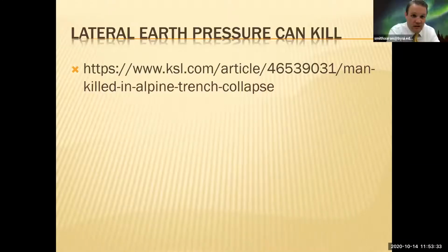Yeah, you will have knowledge that the common construction worker won't understand about soils. If you're ever on a site, you have a responsibility to warn people of the safety hazards they're unknowingly entering into. If you see folks jumping in and out of trenches installing a utility line, and it has pretty steep slopes and it's pretty deep, like Adam said, OSHA requires anything over 4 feet deep to have some type of slope back.